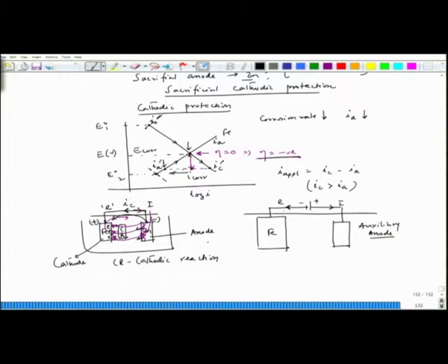Since electrons are coming here, I am sending IC preferably to the iron surface, that means I am going towards cathodic polarization on the iron surface. So, this becomes cathode. So, cathodic reaction happens on that surface and iron is protected. So, this particular process is called impressed current cathodic protection.